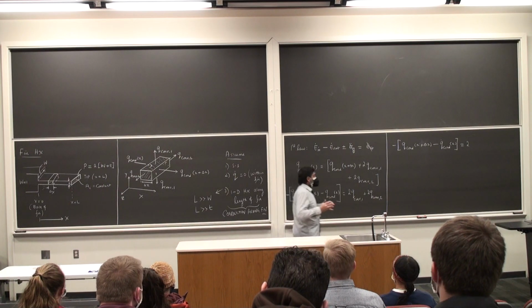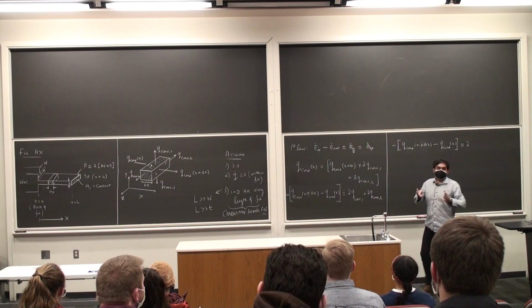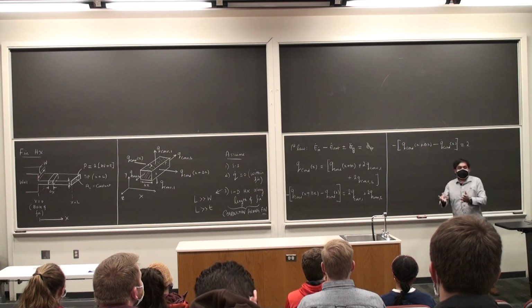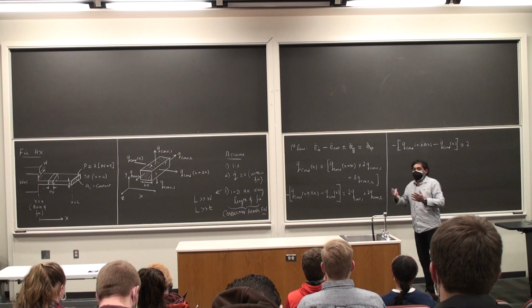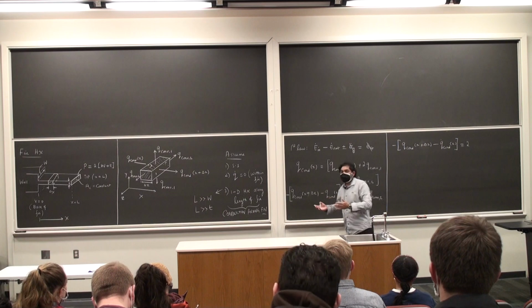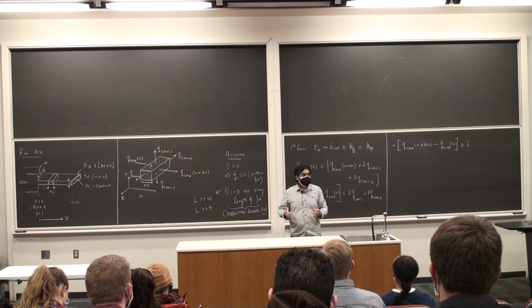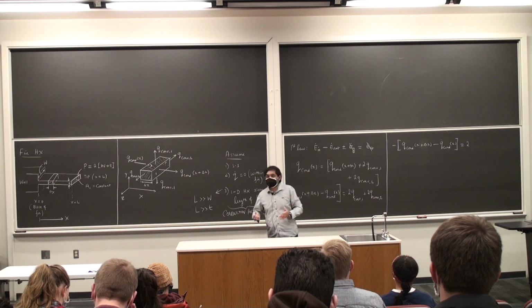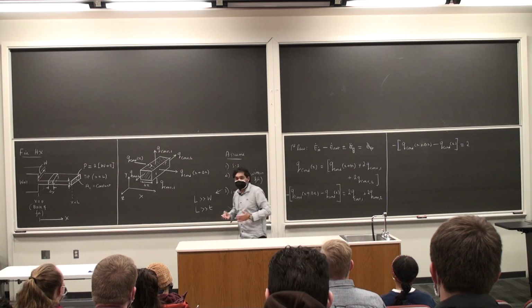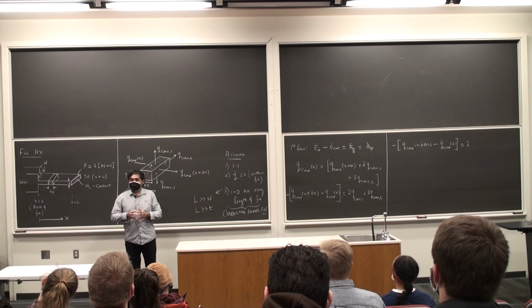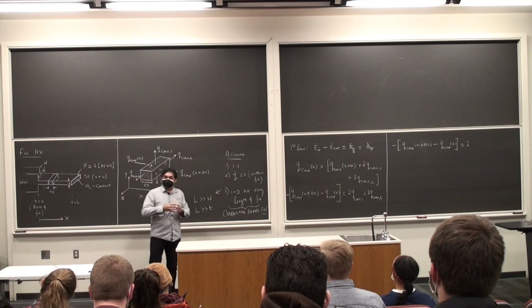What we want is an order of magnitude analysis, almost like a back of the envelope analysis. Given a fin with these particular dimensions, these temperature ranges, these boundary conditions, what's the heat loss rate? Once you get a ballpark number, then you hop onto ANSYS or one of those finite element or boundary element method programs, and then you start doing the actual analysis. What we are doing is an engineering analysis.